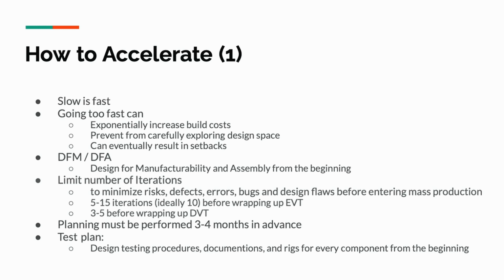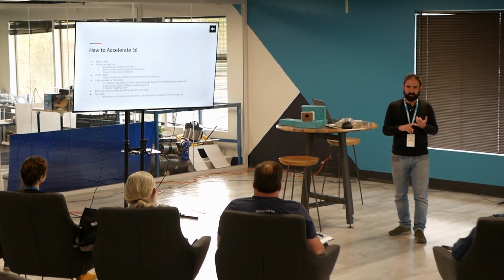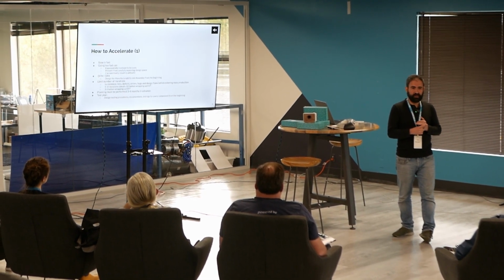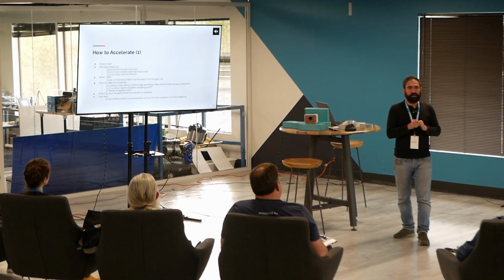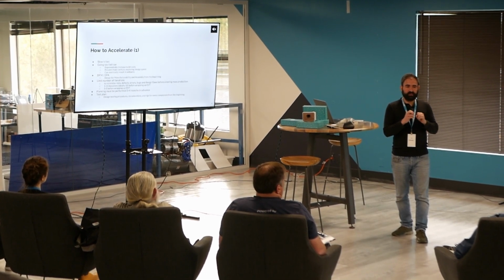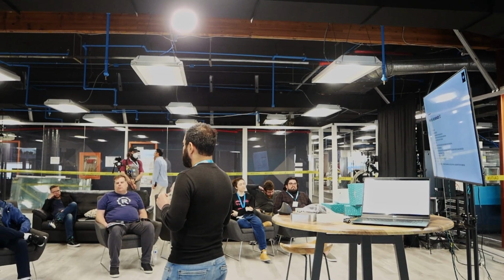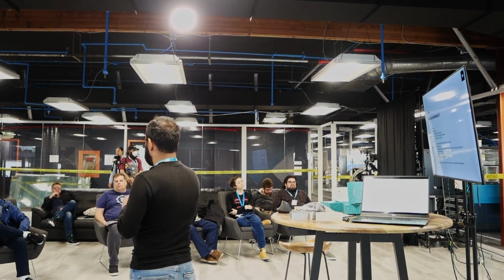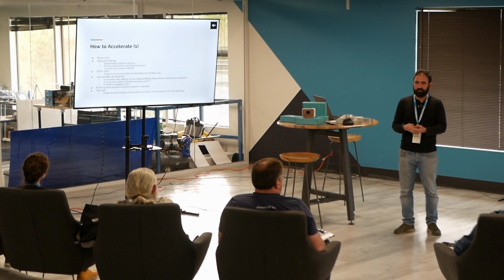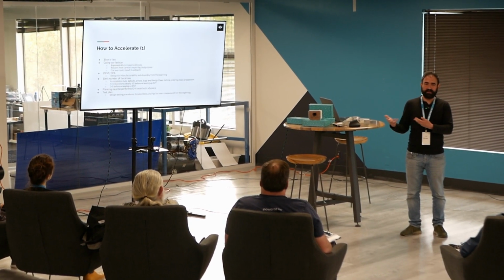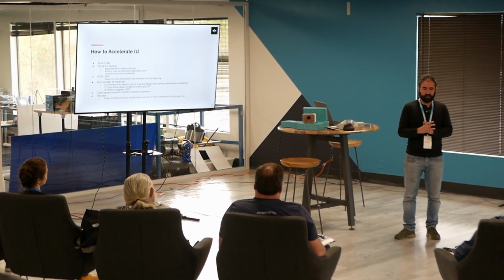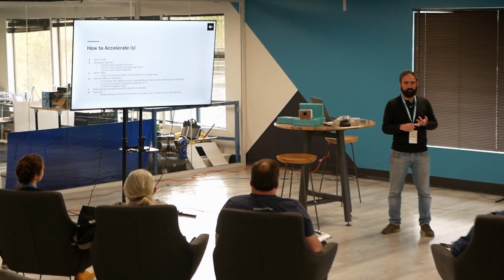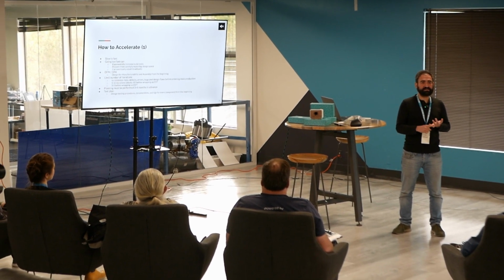One thing that is very important in your design is that when you design things, you have to keep two things in mind. Is this easy to manufacture? If you make your design in a way that uses standard manufacturing processes and even cheaper ways to manufacture it, it's going to make life much easier for you down the road. If you use laser cutters, it's a very easy way to manufacture. But if you need to do die casting of aluminum, then it's a very complicated way of manufacturing. And then DFA is usually neglected. DFA stands for Design for Assembly.